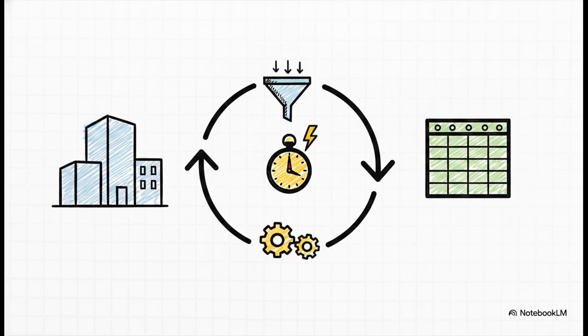A perfect real-world application of this is Excel interoperability. Just imagine having to manually update the names and numbers of 1,000 rooms in a massive hospital project. Nightmare, right? With Dynamo, you extract all those Revit room parameters into a spreadsheet, quickly edit them in Excel, and then use Dynamo to instantly push those updates back into the model. What used to be hours of manual data entry turns into seconds of automated work.